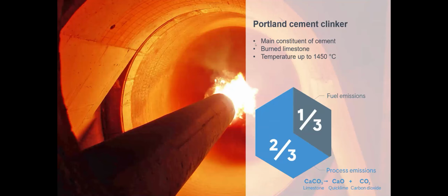You may know that the limestone that we are using is, of course, composed of calcium carbonate. And when we heat this up, it forms in the kiln CO2, which is fully emitted. So we have a CO2 emission diagram, as you can see here, which is comprised of 2/3 coming from the raw materials, decomposition of the raw materials, and 1/3 comes from the fuel. And this is the real topic in our sector.